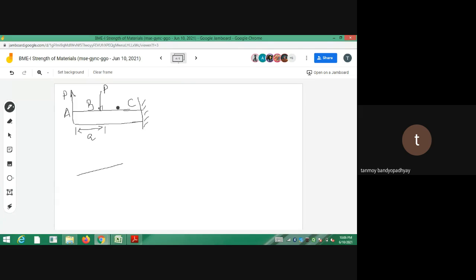So suppose this is the beam, any beam, any cross section. Suppose a beam is having a cross section something like this, and I am applying a force somewhere around here. How is the force acting? If I take the cross section of the beam, you pass a cutting plane or a sectional plane. So this is the cross section. You see this load P is parallel to the cross section of the element. That is why you can tell that the forces plus P and minus P in this case are actually shearing forces. That is why we always have to draw shear force and bending moment diagrams.